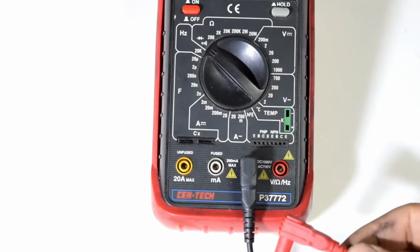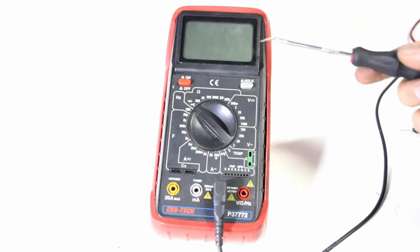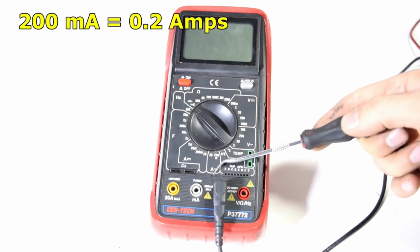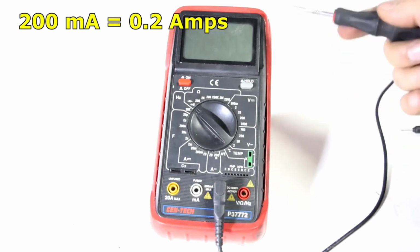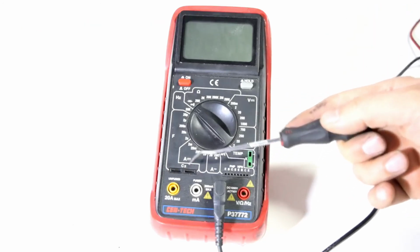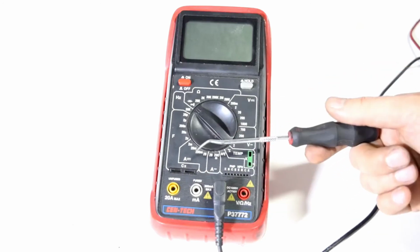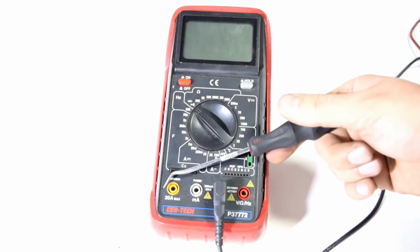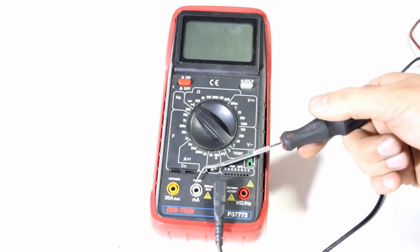Now when you measure amps on this multimeter, you need to switch your test lead from this slot to one of these. Now on this multimeter, this first one is fused, which means if you measure more than 200 milliamps, you're going to blow a fuse inside your multimeter, but your multimeter as a whole is going to be saved. But this second one is unfused on this multimeter, which means if you measure more than 20 amps, you're going to ruin your multimeter.